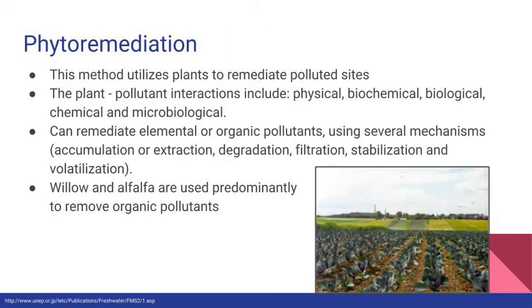The last method we are looking at is phytoremediation. Phytoremediation is the direct use of living green plants for in situ removal, degradation, or containment of contaminants in soils, sludges, sediments, surface water, and groundwater. The uptake of contaminants in plants occurs primarily through the root system, in which the principal mechanisms for preventing contaminant toxicity are found. The root system provides a high surface area that absorbs and accumulates the water and nutrients essential for growth, as well as other non-essential contaminants.